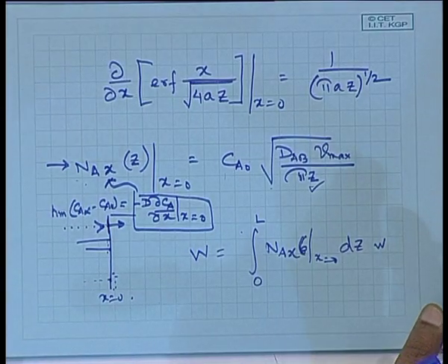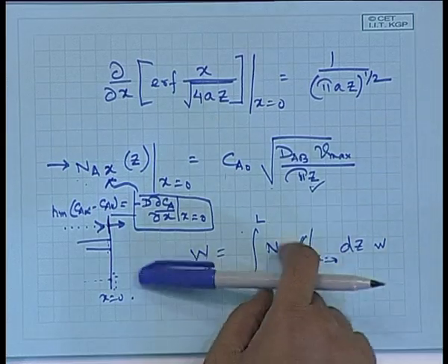So, what we have in summary, what we have done in this class is we have seen a problem which is a coupled problem, a fluid flow problem coupled with mass transfer. We could decouple these two by making an assumption that viscosity etc., these properties are not going to be altered, not going to depend on the presence of A molecules in the system, which would be true if A is sparingly soluble in B. Then we have seen that the diffusive flow in x direction predominates, whereas the bulk flow in the z direction predominates.